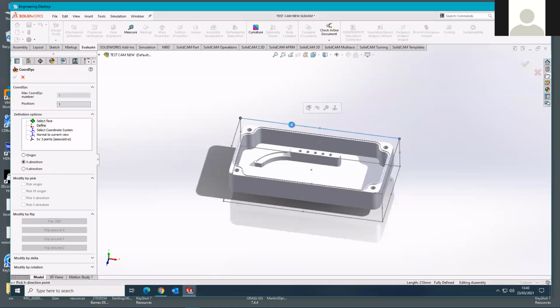So click on there. It then moves down to the next piece of input, which is asking what you want to consider the Y direction. And again, convention is that the X and Y axes in normal mills are the horizontal movement axes within the mill. The Z tends to be considered the axis that the spinning spindle can move up and down.